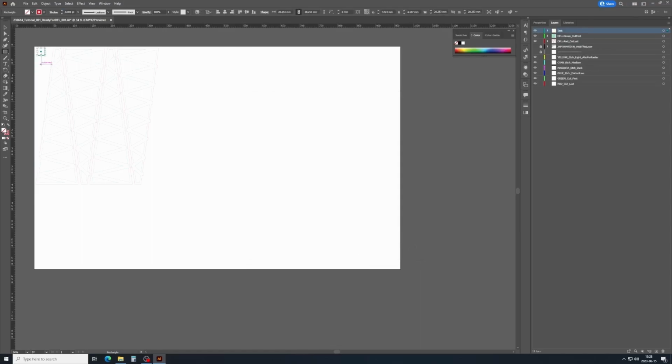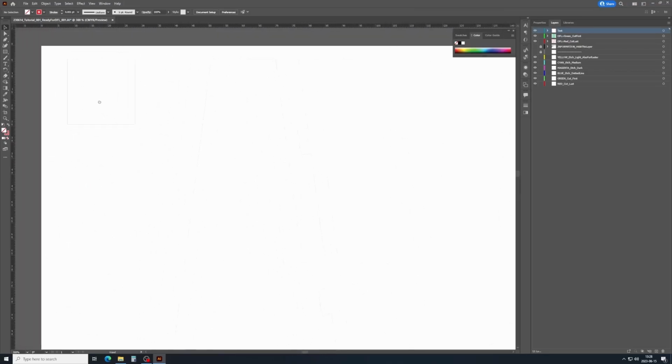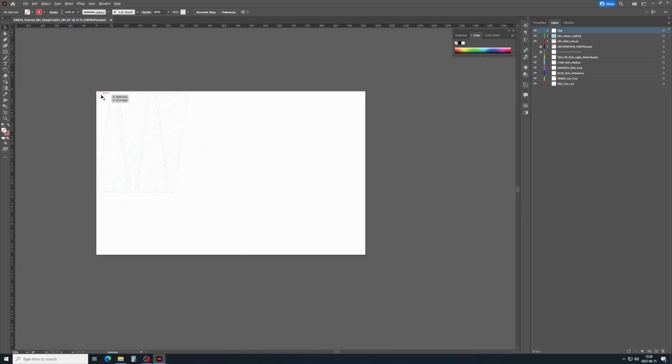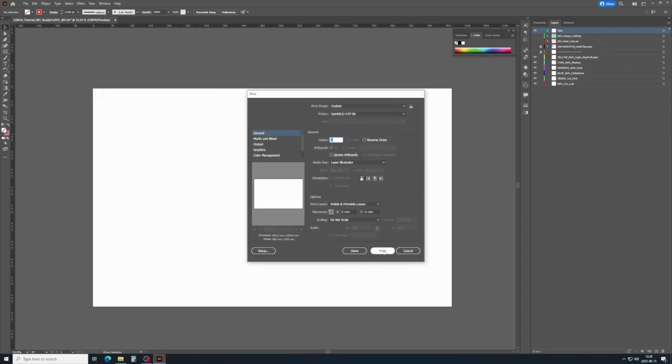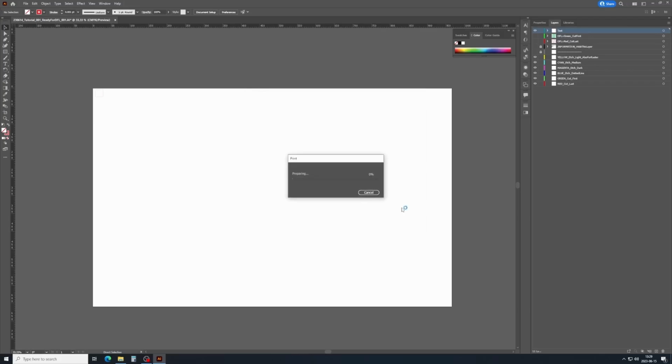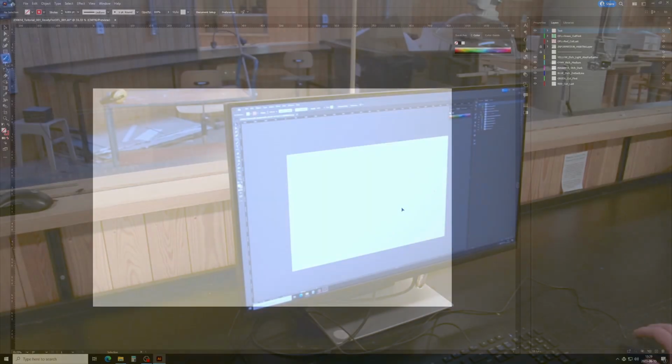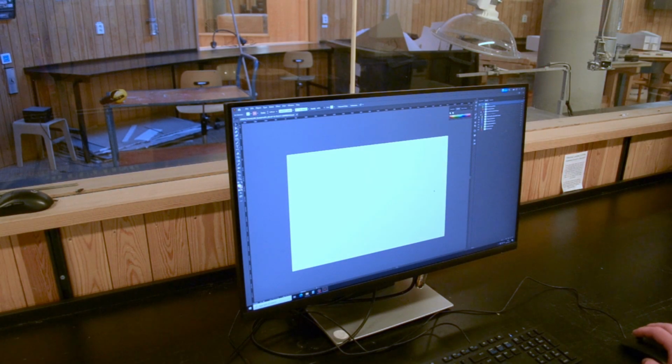Create in a separate layer a small test rectangle outside of your drawing's contents and assign proper stroke color, stroke thickness and fill color, and hide the other layers so that you can separately send only the test objects to the laser cutter. Sometimes at this stage, Illustrator throws an error that the illustration cannot be printed, but it usually works when you print again without changing anything.